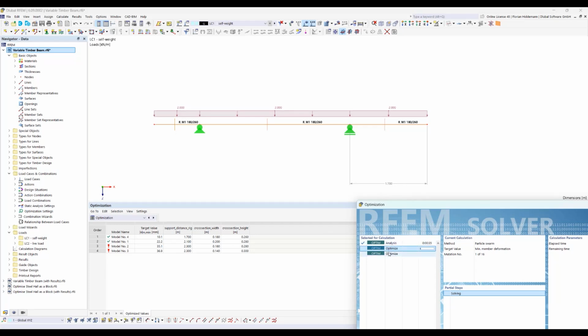And now it goes to a second step. It now uses the results from the analysis. Here it is combining the two most influential parameters with a particle swarm that calculates 10% of these possible combinations. And the 10% is now only 16, and it's not 181. I'll show you it afterwards.